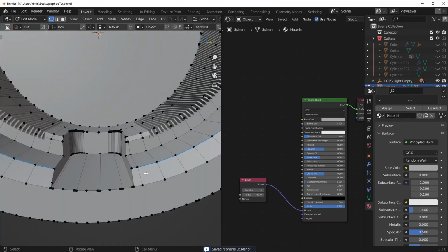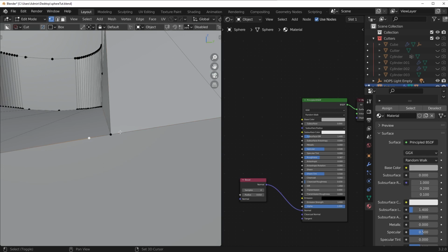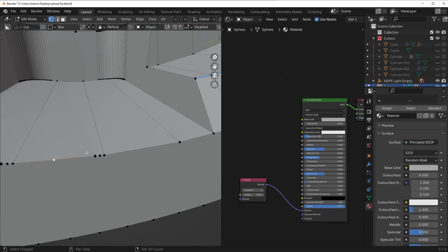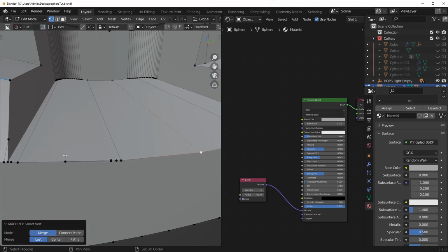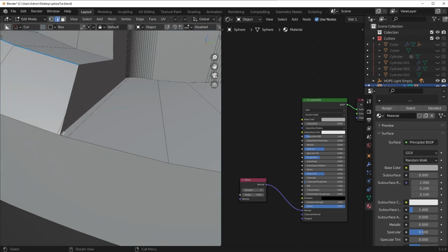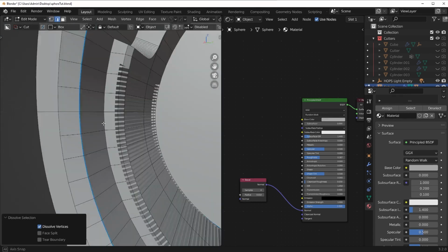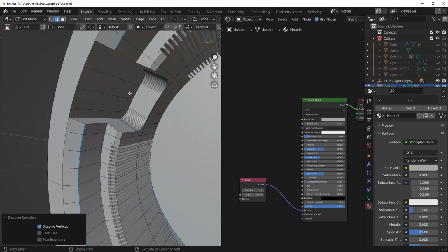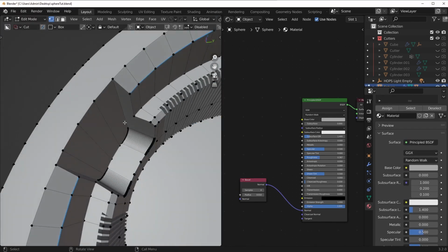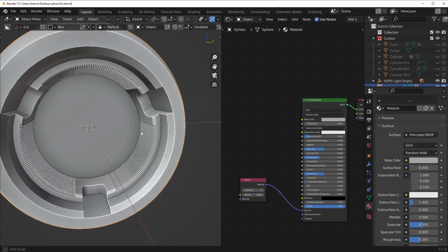And if we go down here, just gonna do the same thing to this last portion. Gonna merge those together. Going to merge these. And then these, and I don't really know why these vertices got here. It's just something weird that happened with whatever boolean we were using. So I'm not too worried about it. I'm just worried about fixing it. Then we can dissolve out that edge. Merge that one there. I could just dissolve out that one. And basically we're going to have a much cleaner result here. No weird or nasty geometry. It's all merged together exactly how we want it. So it's a little bit cleaner that way.